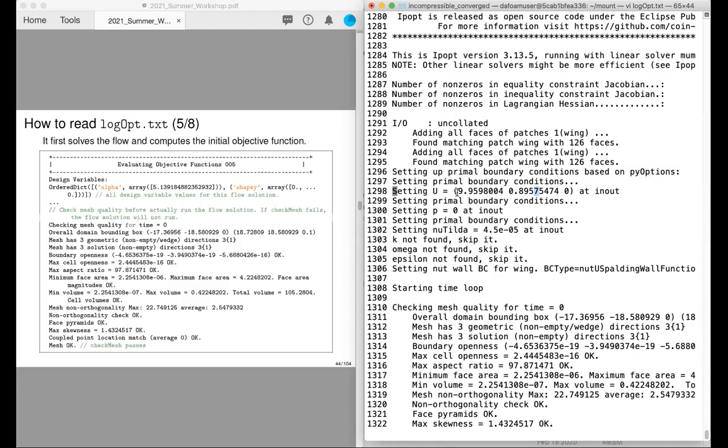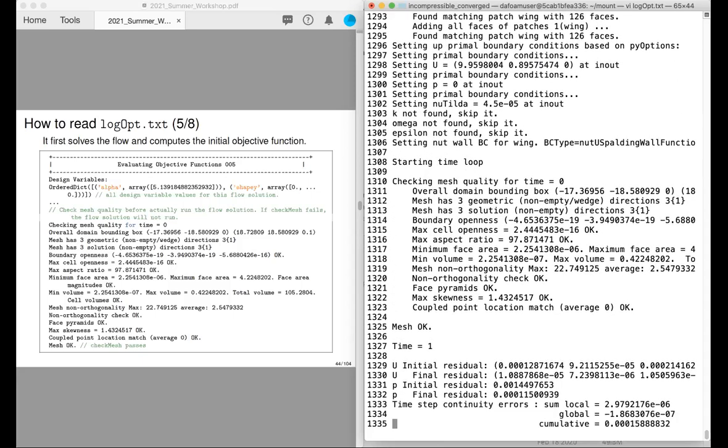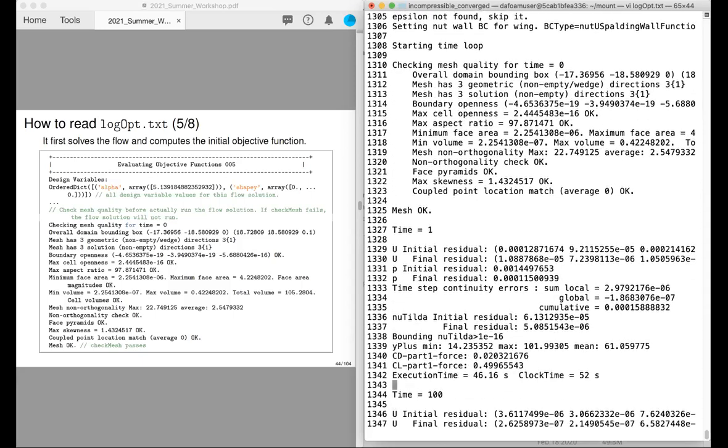This is done fully automatically by DAFoam: based on the velocity magnitude and angle of attack, it will prescribe the velocity components for velocity, for pressure, and for the turbulence variables. It will override whatever boundary condition is provided in the OpenFOAM 0 folder. So keep that in mind. Now, what's next is that we'll start some flow simulations, time equals 1.